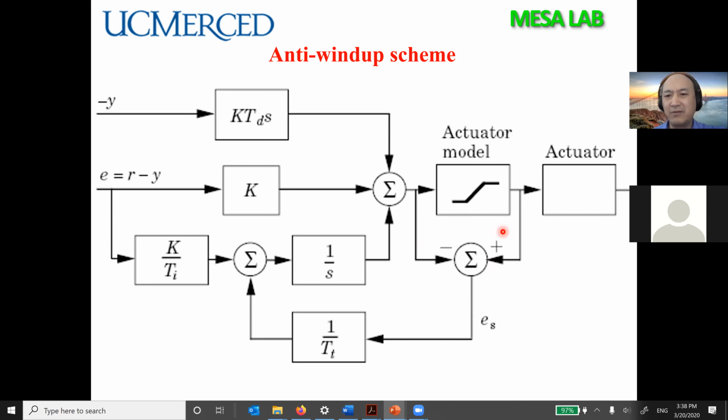When I'm not in saturation state, this should be 0, okay? When I'm in saturation state, this one is bigger than this one, so this is negative. I pull out the negative times a coefficient and put it here. It's just like I pull out the integrator's input, so that I get out of saturation as quickly as possible. This is D, this is P, proportional control. But why do you have a minus Y in here? Where is my R?